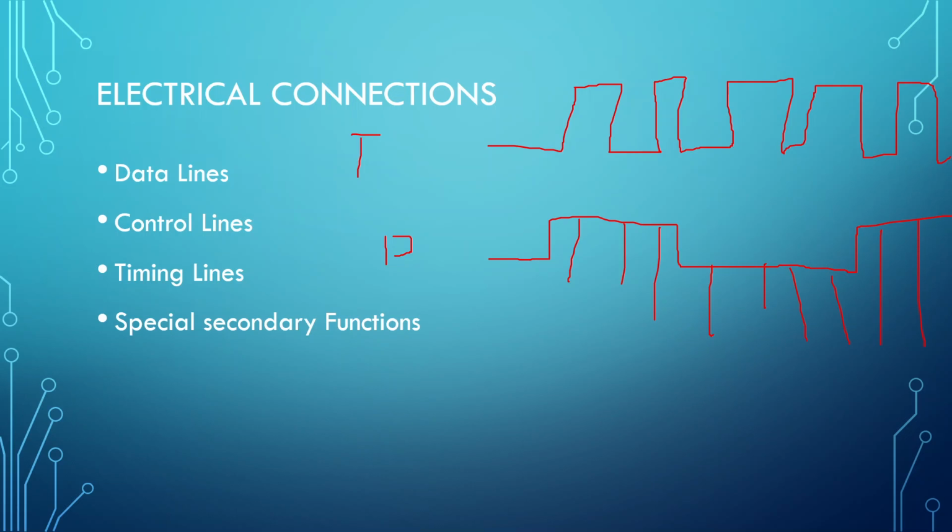Most of the time when I've dealt with equipment, I've not done synchronous, I've not dealt with handshaking, it's all TTL based, it's just, are you sending data or not data? It's simple, 3 wires and I'm done, so I haven't really had this big of a problem, which is nice. Some manufacturers omit the control lines from the RS232 equipment or assign unusual applications to them. So again, lack of consistency.